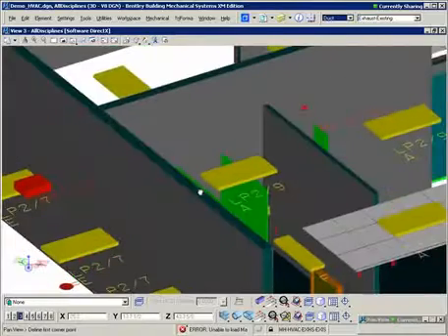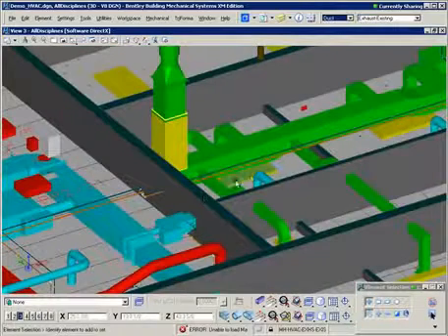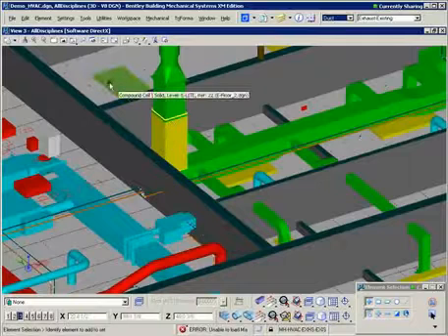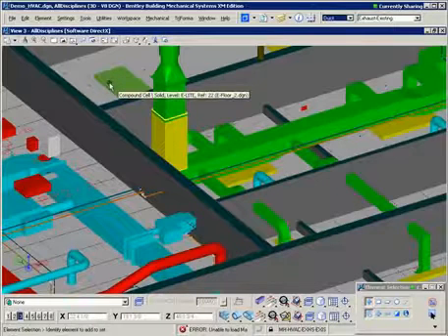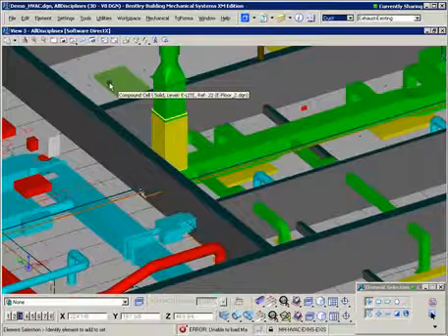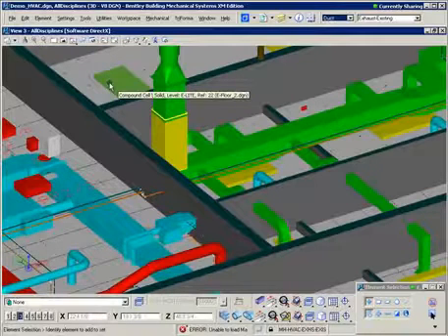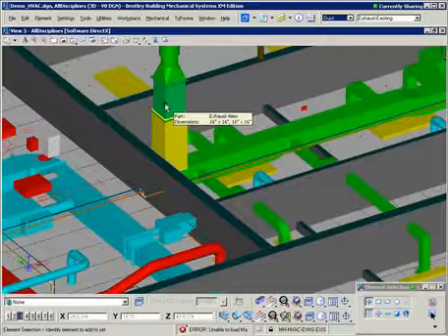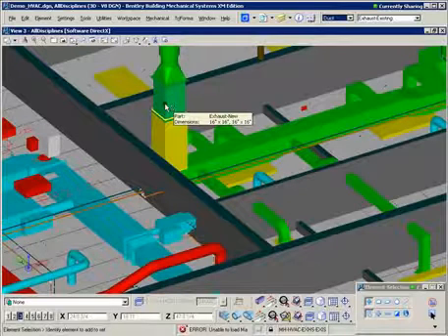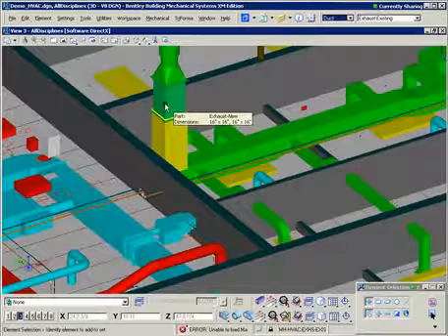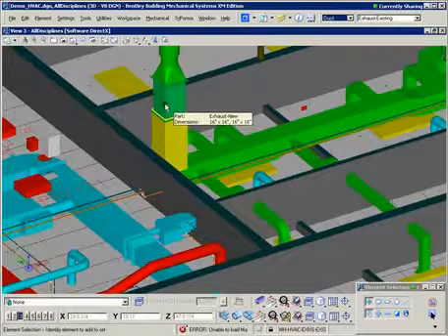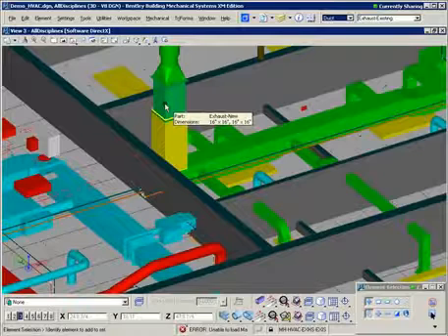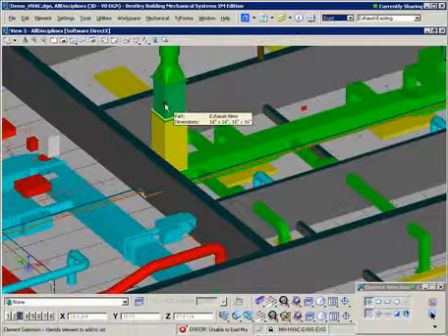If we just move a little bit to the side, these yellow panels here would be the electrical panels. So you can also see that at the flyover you see in which file they are and on which level they are, and in this case it's an electrical file. At the flyover we also get information about the elements we are looking at, and in this case it would be the part information, where the part would be supply air, return air, and so on. In this case it would be exhaust air. You also see the dimensions of it.